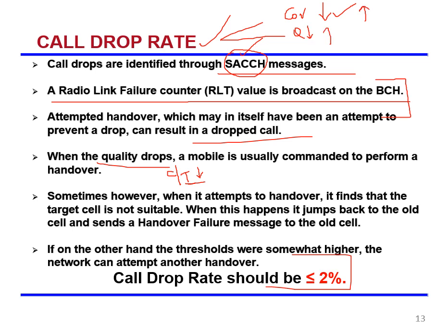For quality, you have to do frequency planning, or the sources of interference should be determined and addressed. For handovers, verify whether the handover failures are because of neighbors not being defined, and proper neighbor definition should be there in the OMCR, and we will verify it.